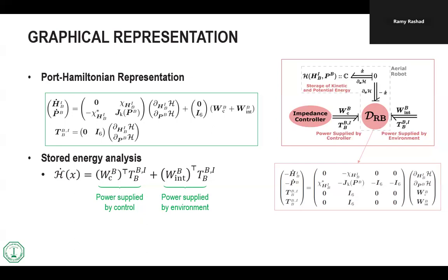For example, there's a famous program called 20sim. With it, you can actually build the system. Instead of writing a mass spring damper as a second order differential equation, you can just draw it like this, run the simulation, and it simulates everything for you.